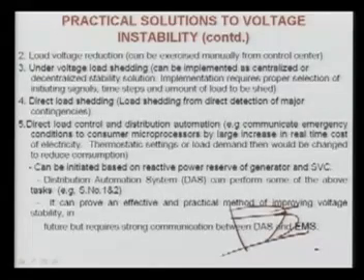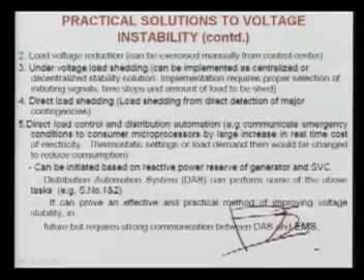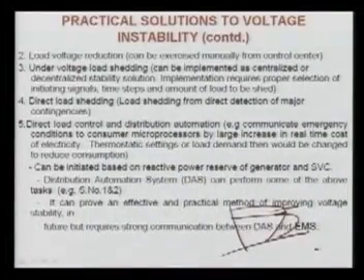Under the load shedding schemes, as you know, there are two types. One is the load frequency control, where if frequency falls, normally we try to shed a few loads so that we can improve the frequency of the system, and that is what we are talking about in transient stability. In a similar fashion, we can have relays such that if voltage is low they shed the load, and then we can again improve the voltage stability margin.